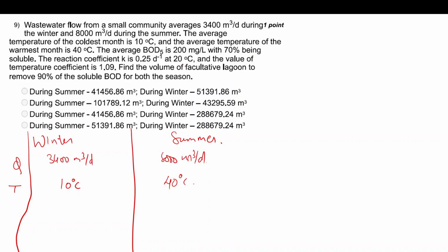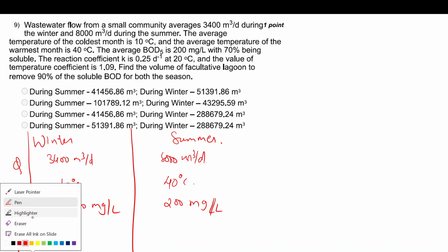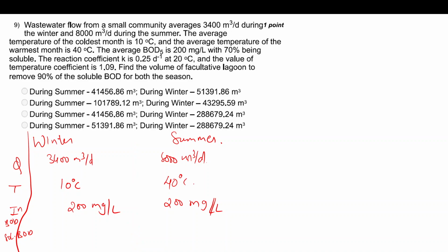So inlet BOD is the same for both, 200 milligram per liter, out of which the soluble BOD is nothing but 70%, or 0.7 times the actual BOD, which is 200.